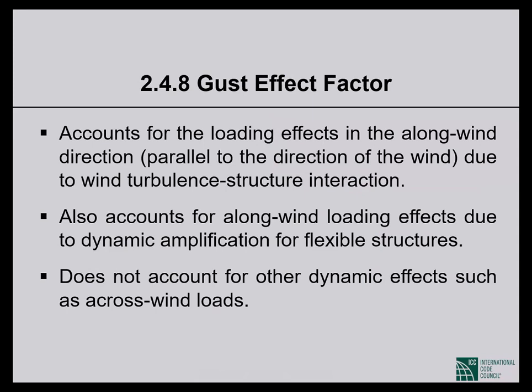It accounts for the loading effects in the along wind direction, parallel to the direction of the wind, due to wind turbulence structure interaction. The gust effect factor also accounts for along wind loading effects due to dynamic amplification for flexible structures. So flexible structures react more to wind than rigid structures, and that is taken into account through the gust effect factor.